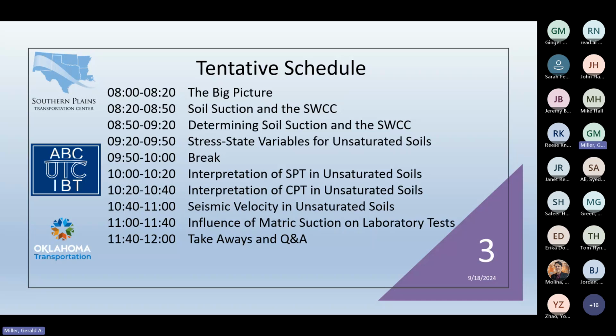After that, I'll get into some discussion on interpreting standard penetration tests in unsaturated soils. We use the SPT pretty extensively in practice. I think almost every subsurface investigation includes some SPT work. Sometimes the SPT is the only indication of the mechanical behavior of the soil that we have for a project. And so we have to think about what it means if we do that test during a dry period or during a wet season, and how that influences the interpretation of the results.